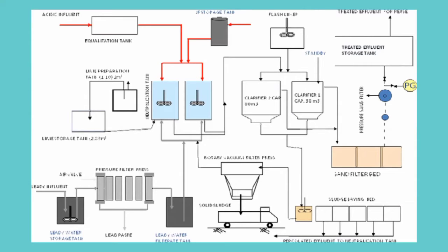Wet scrubber is provided for air pollutant removal in industries. In wet scrubber, the polluted gas stream is brought into contact with scrubbing liquid by spraying it with the liquid. It can also be done by forcing it through a pool of liquid or by some other contact method so as to remove the pollutants. The design of wet scrubbers or any air pollution control device depends on the industrial process condition and nature of the air pollutants.